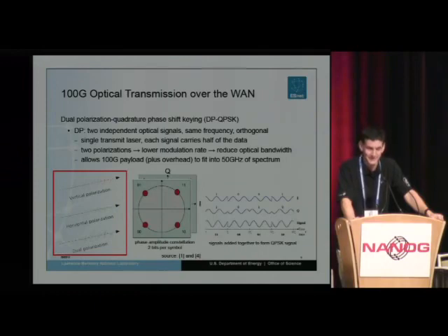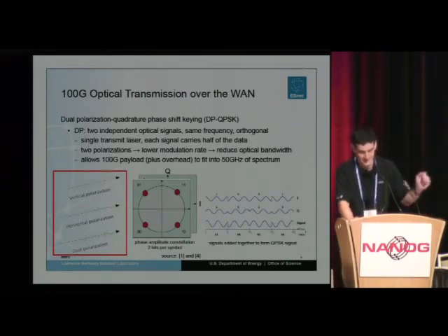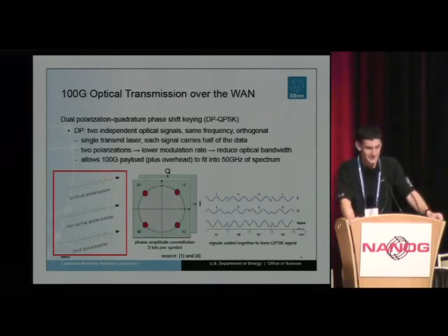In the past, in order to increase the channel line rates, going from 1 to 10 was simply a matter of just increasing the symbol rate. Symbols were just binary intensity modulation. We could go from 1 to 10 with a single carrier without having to do anything particularly fancy. The commercial success of 10 gig has really led to quite a cost reduction of all these 10 gigabaud components. So instead of changing the symbol rate drastically, 100 gig has really looked into other ways of leveraging the existing technology and trying to find other ways to increase the channel bit rate.